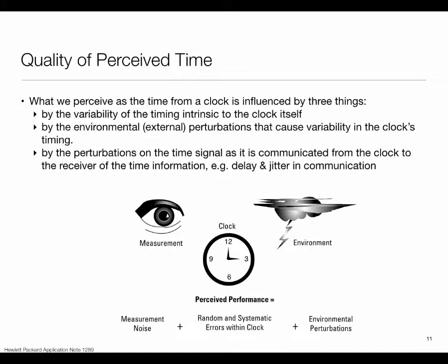Vibration, yeah, or acceleration more broadly. If you put it onto something which is swinging a lot, or a car which is accelerating, time is affected. Of course, relativity tells us that too, but here it happens for non-relativistic reasons, which is simply that as vibrations happen or as things are shocked, there are minor changes in the mechanical dimensions of the crystal, which cause this problem. So there are many factors by which ambient conditions affect things.